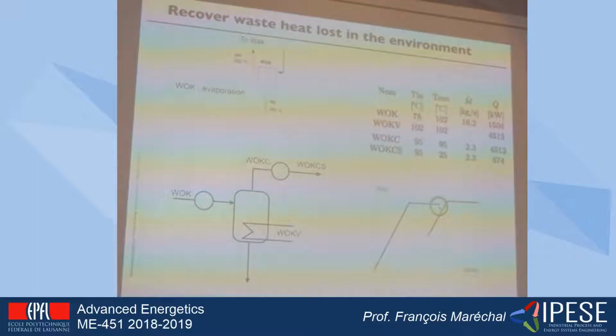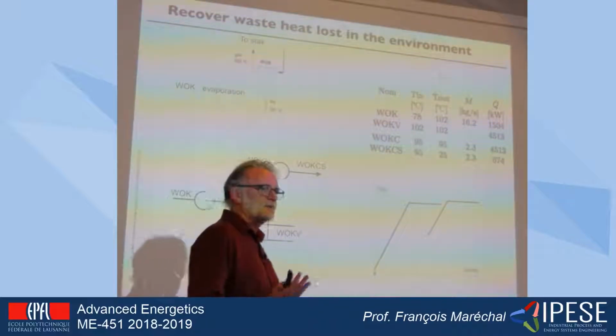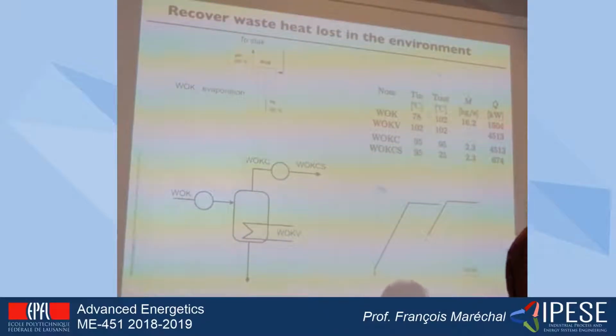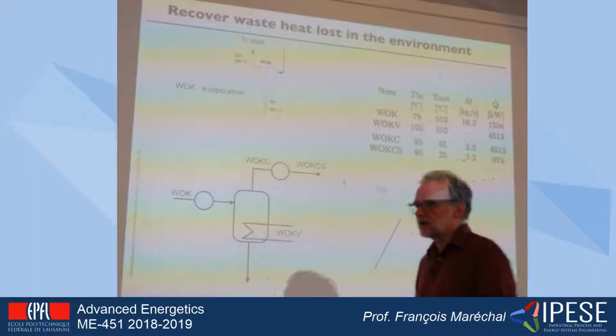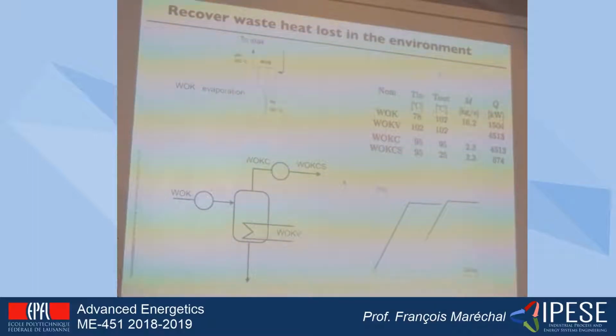And on the other hand, I will have this stream, which corresponds to the condensation of the steam that is here, and then the cooling down of this one to the ambient conditions. So it means that I have defined now the requirements, not only by a heat to be supplied to a system that is going to make the evaporation, but a list of steps: preheating, evaporation, condensation for heat recovery, and then cooling down. And by doing this, I have defined the streams in a rational way.